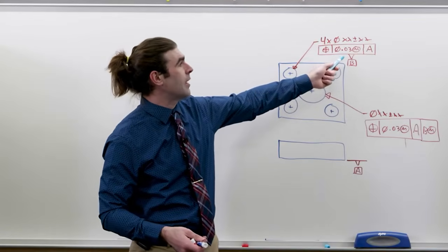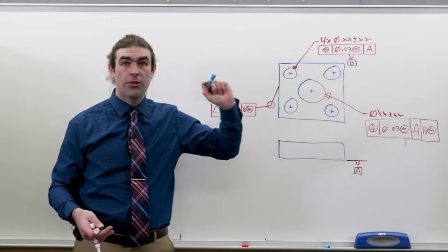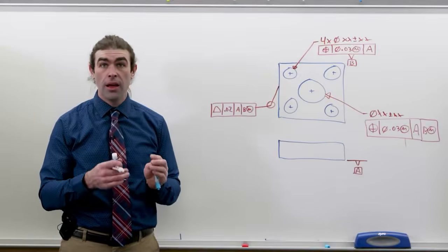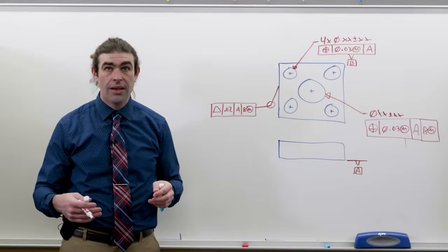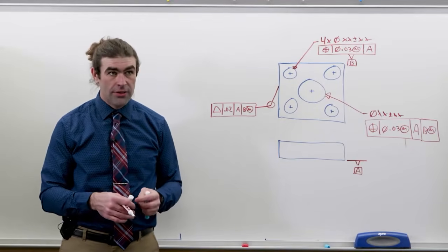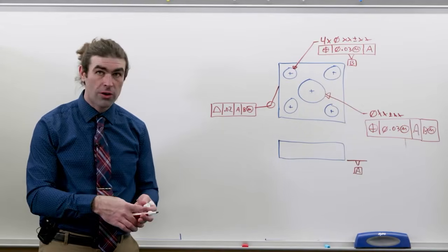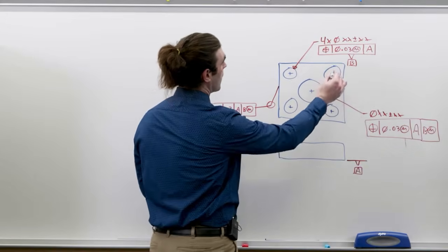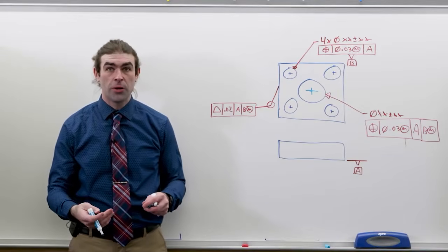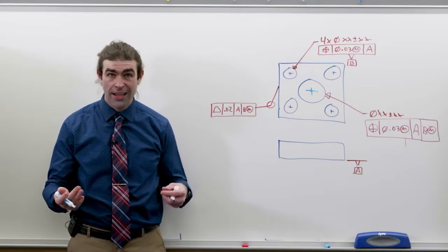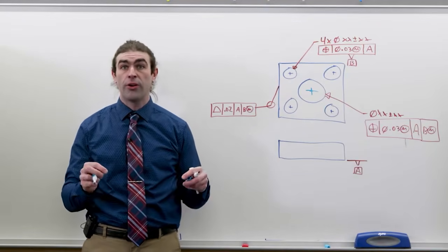So position, diameter 30 thousandths MMC to datum A, but this pattern establishes datum B. And then all of the other features of the part are going to be relative to the pattern. Now the tricky thing with the pattern is that none of the holes individually is the origin for measurements. The origin is actually in the middle of the part, right? So that pattern creates an axis in the middle of the part, or you could think of it as 2 planes in the middle of the part. You essentially are going to measure from the center of those 4 holes.